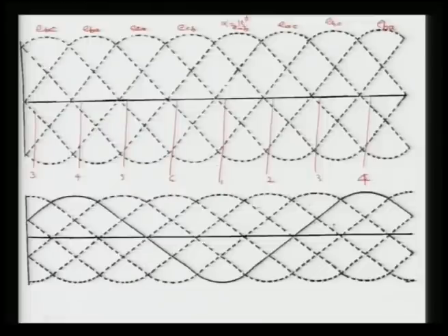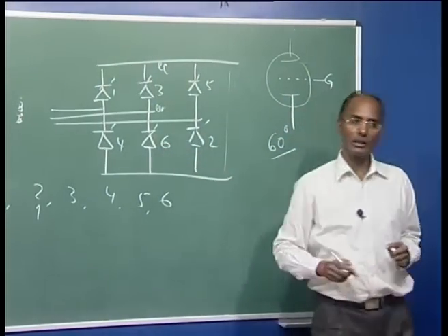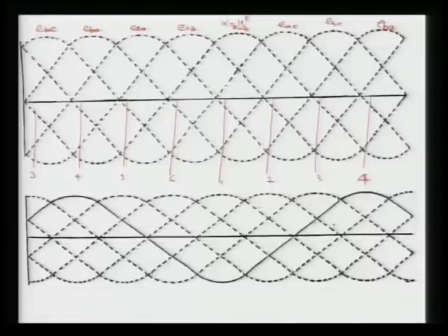We are giving the pulse here in the rectifier mode. You will just see here, 6 and 1 are conducting, it is A, and here it is B. EAB is the output voltage, and EAB output voltage here it will be this much. So, here it is starting at this moment. No, this is just 1 is given. So, here 6 and 1 are conducting. Now, we are coming here.